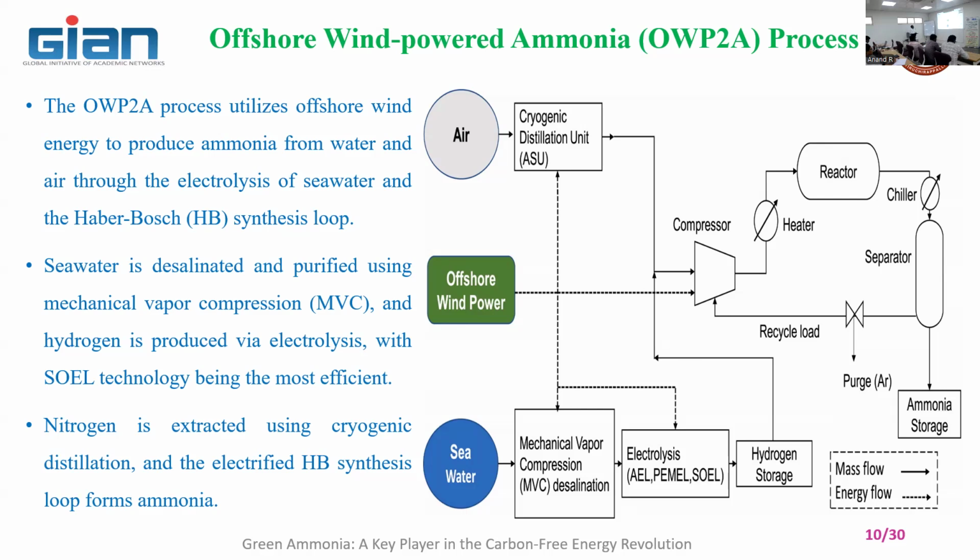After the temperature comes down to the expected temperature, you separate out the ammonia. Along with the ammonia, nitrogen and hydrogen gases also come out, and so many other things come out. By chilling, we are not only recovering the waste heat but also separating out the ammonia from the different mixtures.